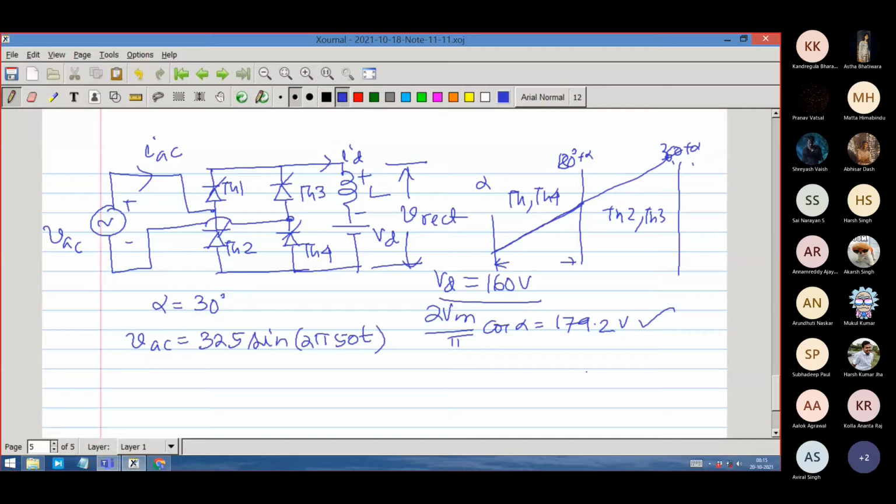Here, suppose I apply a DC voltage to an inductor, the current continues to increase, then that is not a stable situation. There is nothing to analyze. It will be infinity. If I wait for a sufficient amount of time, the current will build up to an infinite value. So that is not an interesting situation, or not a steady state operating condition of any circuit.